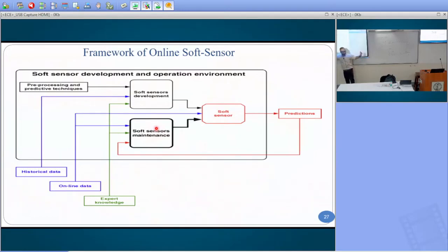If this is not working, the other way is to stop this. Don't send it, because it's already performing badly. Again, take the data and re-identify the model. That is another way. The third option is online training. You're trying to adapt your model online. You take recent data and again do all the analysis of model parameter training, but using a recent window of data. It's like window-based training. You take recent historical data and keep moving it. So it's called online training of your model.